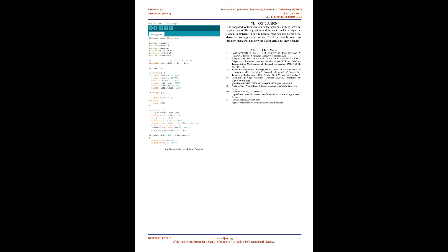B. Software design. The programming of the whole system is done in Arduino IDE, which is open-source software used to program any Arduino board. A pulse signal is generated and sent through the trigger pin of the ultrasonic sensor. It reflects and is received by the echo pin whenever it strikes an object. The distance between the sensor and the object is determined using the received data. Based on the calculated distance, Arduino sends instructions to the LEDs and LCD.